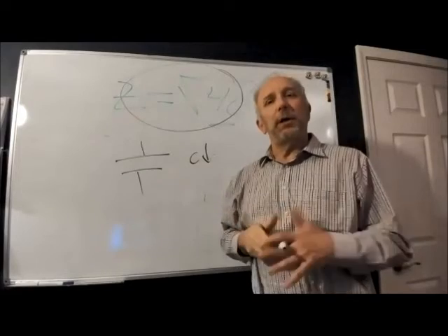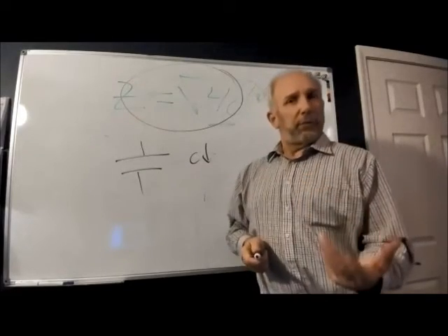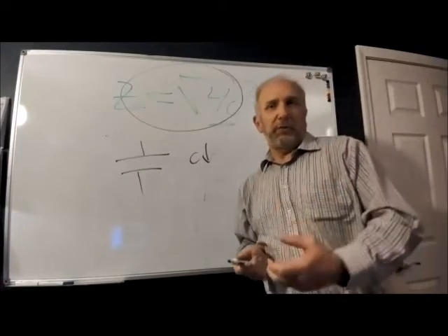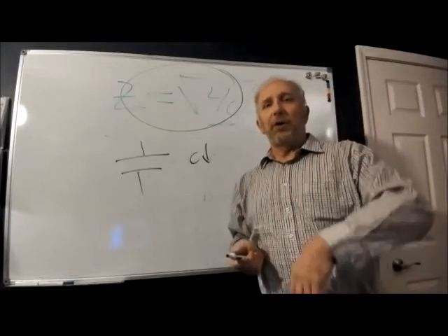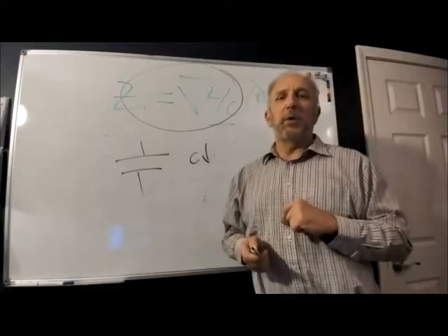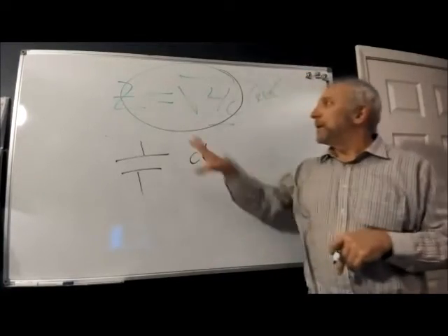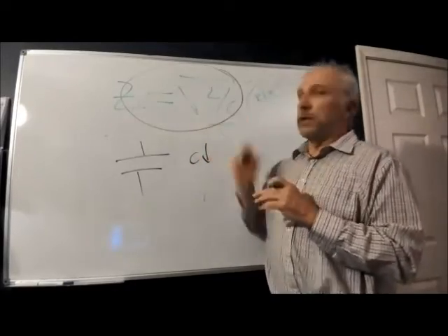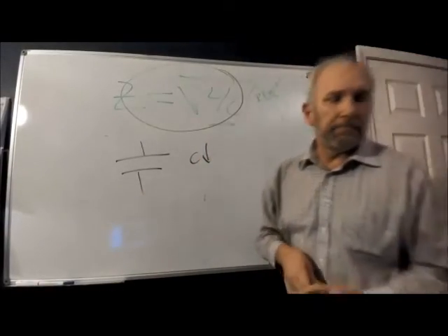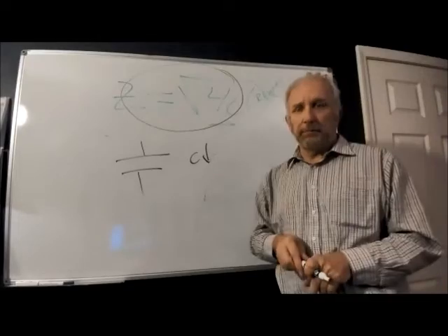Which is why you'll see different transmission lines have different characteristic impedance. RG58, which is 50 ohm, RG59, which is 75 ohm. We have something called parallel wire, which is 300 ohm, and so on. The important parameter is to understand that the impedance is a function of the inductance and the capacitance. Okay, questions on that? All right, let's talk about a printed circuit board.